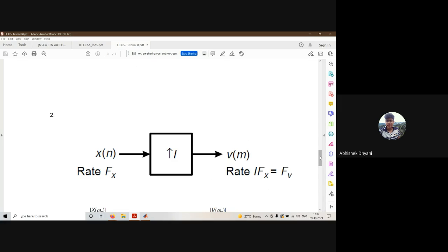And so basically as a result of passing through it, for example if xn was x naught, x1, x2 and so on, between x naught and x1 there will be I minus 1 more samples inserted, and then we can interpolate them when we pass them through this low pass filter block. That was the idea.